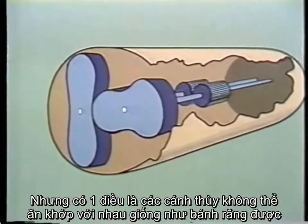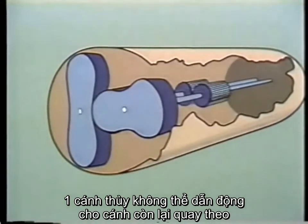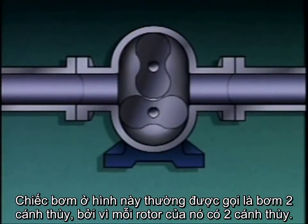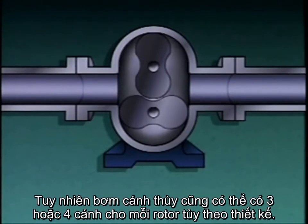But because lobes cannot mesh like gears can, one lobe cannot drive the other. So all true lobe pumps require timing gears to coordinate the rotation of the lobes. The pump shown here is often called a two-lobe pump because each rotor has two lobes. But lobe pumps can have as many as 3 or 4 lobes on each rotor, depending on their design.